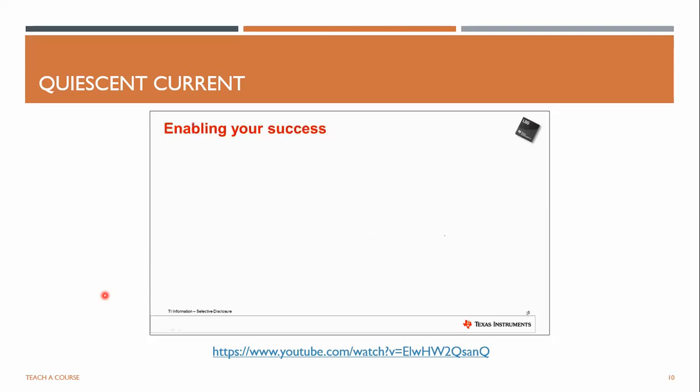An enable or shutdown pin is another simple solution if you're designing to conserve battery life. Smartwatches, fitness trackers, phones, and even drones can employ the solution for a battery boost. Drones, out of all the consumer electronics that were mentioned, spend very little time in standby mode because they're usually only idle pre or post flight. However, you can still save battery life by shutting down LDOs attached to those modules not needed for flight.